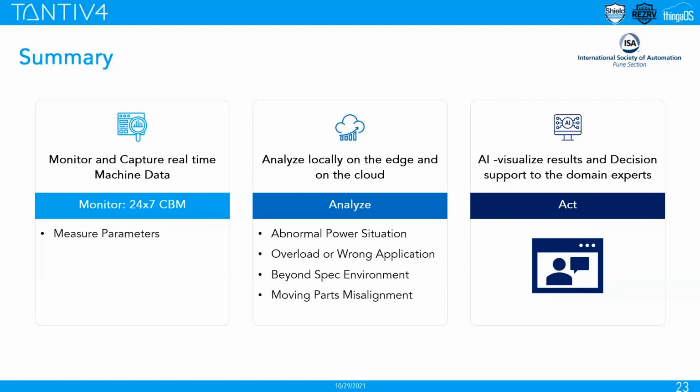Of course, the spinning looms, we can install this on each of the looms, and we can see its operational efficiency, how much is the rated power consumption, how much it is changing, what is the effect of voltage unbalance, or there are many mechanical components that also create spikes in the voltages.